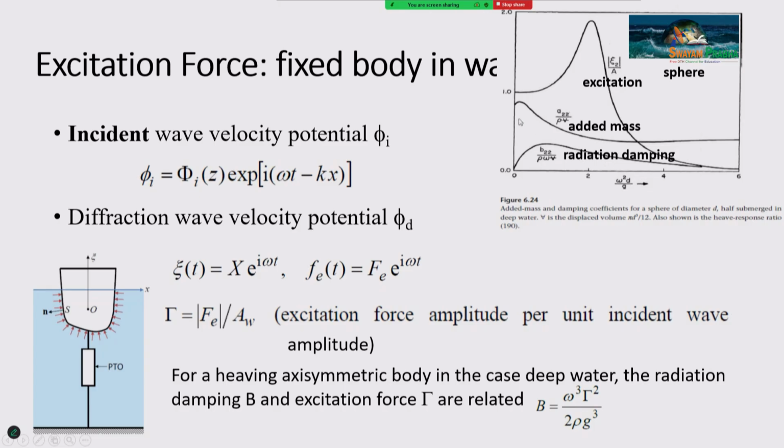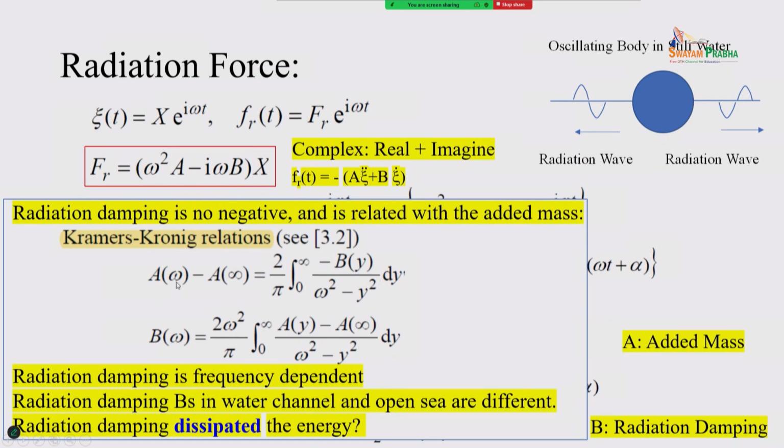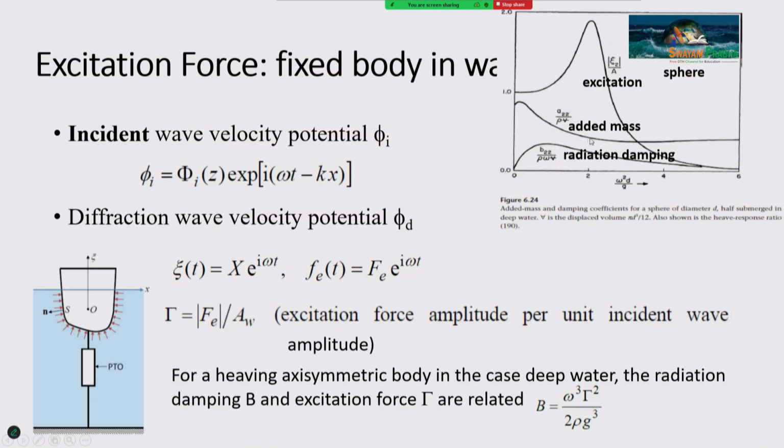I mentioned that this figure I'm going to come back to again. This is the normalized frequency. This line is the frequency-dependent added mass. Added mass and radiation damping are related. This is the radiation damping term, and here you show the excitation force, which you can calculate using the radiation damping.